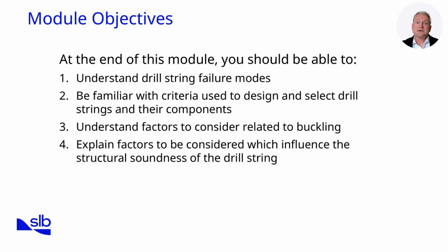The module then introduces two critical design parameters, the bending strength ratio BSR and the stiffness ratio SR. BSR helps evaluate the resistance of connections to bending stresses, while SR measures the relative flexibility between drill string sections. Both ratios are indispensable in predicting performance under downhole conditions.